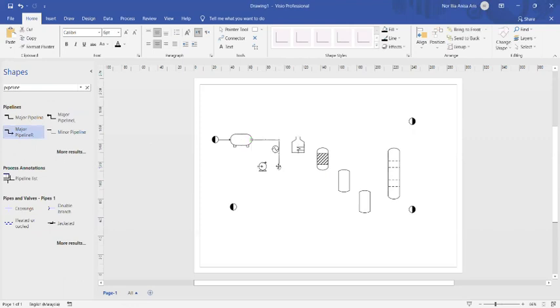Connect to the pump, and then from the pump we should insert into the heat exchanger first. Make sure, and then after that, insert into the heat exchanger before we proceed to the fire heater. This is the product at the upper. So we have the fire heater, and straight we go to the reactor.